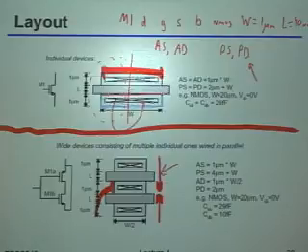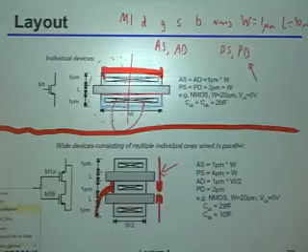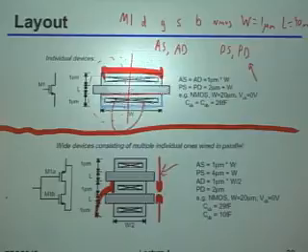Okay, now, the other thing I just want to briefly mention, because for better or for worse, you'll probably run into this issue, is that there's a lot of, I shouldn't say debate, but a lot of confusion around the fact that oftentimes you lay transistors out this way. In particular, if you're trying to simulate things or even draw them in Cadence, you'll usually see one of two parameters that you can specify. One of them is a so-called M factor, and the other one is usually called NF, or number of fingers. Okay?